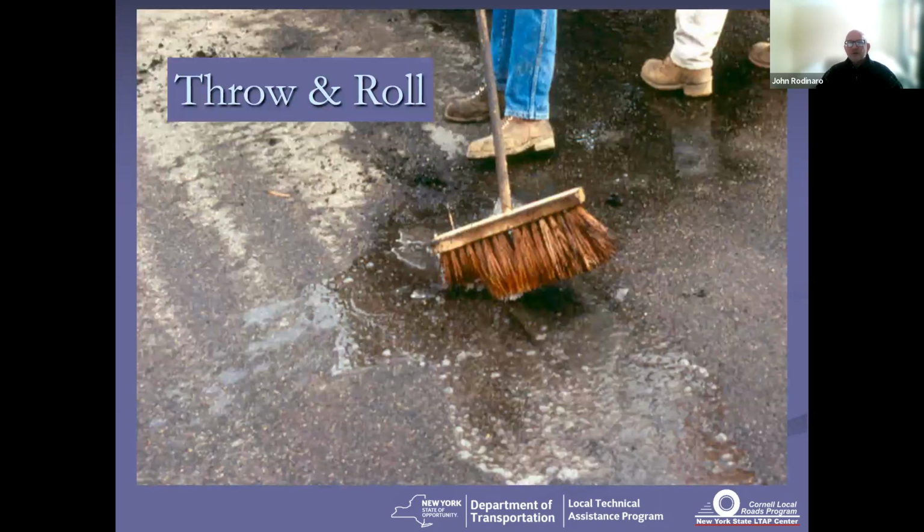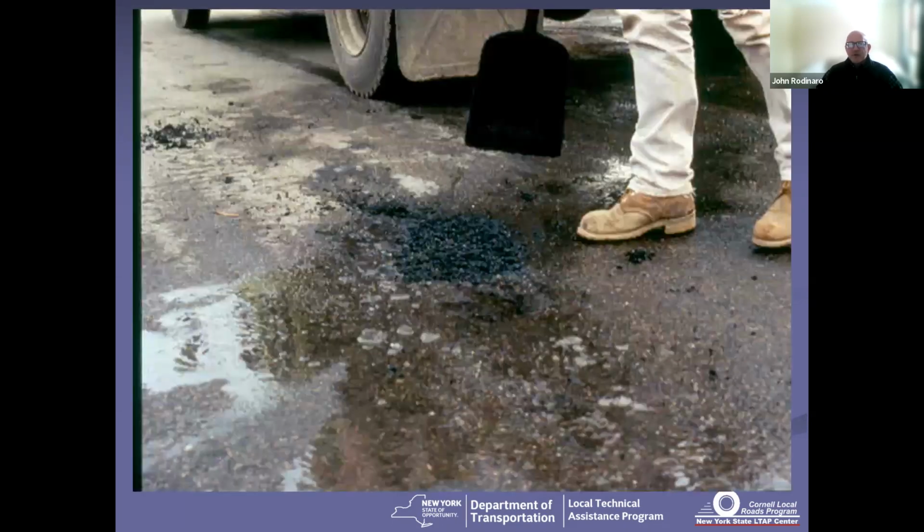So what we really strongly encourage is the throw and roll technique. You want to start out by getting as much water and debris out of the hole as possible. It's important, but not critical. You're going to hit it with a shovelful. You're going to fill that hole with your modified material. If you take a close look at that material, you can see it's glossy and looking sticky as can be just from this picture. And it really is. That stuff is highly juiced up. It's already compacting under its own weight in that picture.